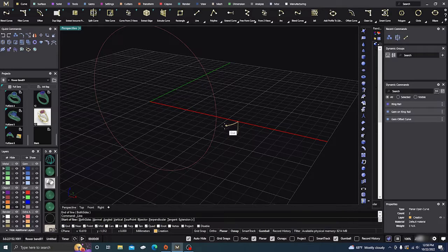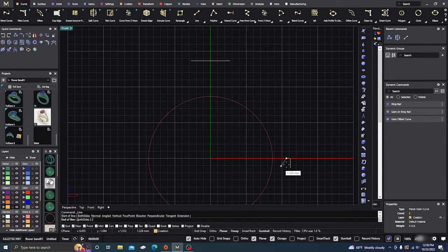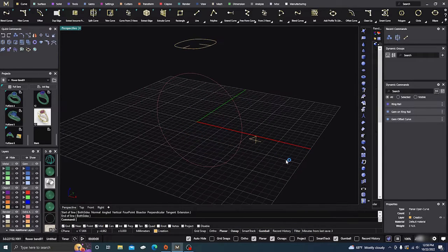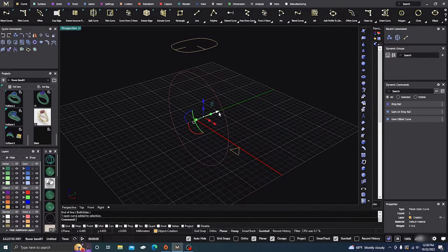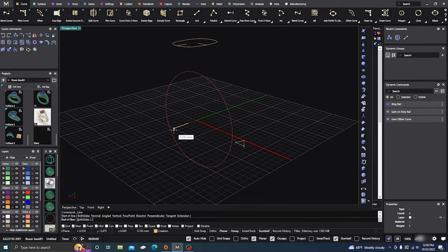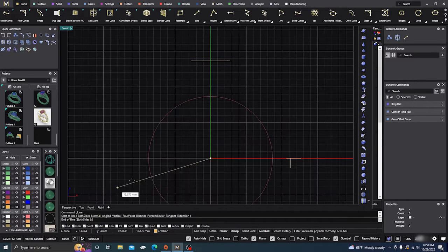And I'll take that and we'll go to the front view again, and holding down shift, select that, go back to perspective, and I'll start another curve, but I'll go from F4 back, holding down shift this way, and I'll take this curve and select this, and we'll put it at a -5 and hit enter. And then we'll go ahead and get another curve, select it here, go to the front view, holding down shift here, and then we'll need another one going this way.